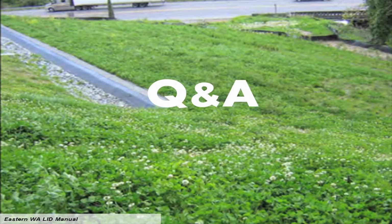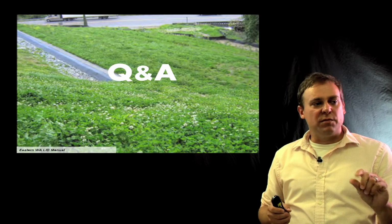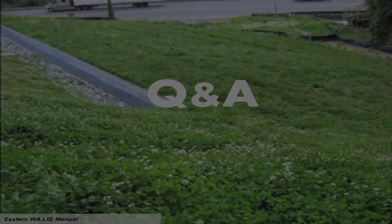And I'll just throw in one more point on siting. Really think about turning movements where you're doing porous pavements. In some cases, if there's a lot of parking going on, that's where you can pluck off the subgrade or the surface, especially of a porous asphalt. You'll see that happen a lot more, as it'll wear quite a bit more where there are turning movements going on, because that's a lot of load. So be cognizant of how you're designing that. And again, if you redesign your system, you can have the drive aisles be porous and your parking stalls themselves, where the turning is going to happen, be conventional asphalt. So not the entire surface needs to be permeable for the system to work.